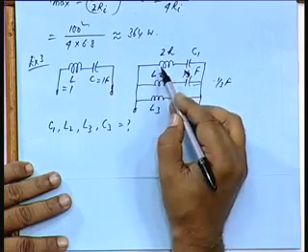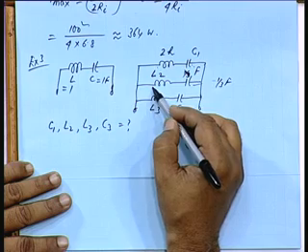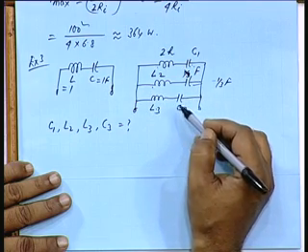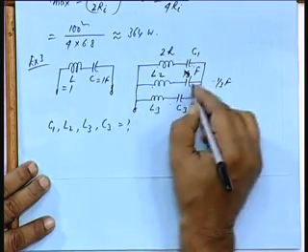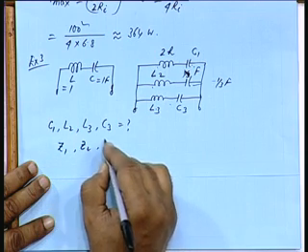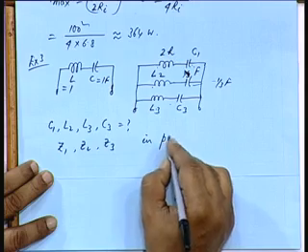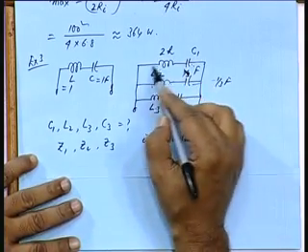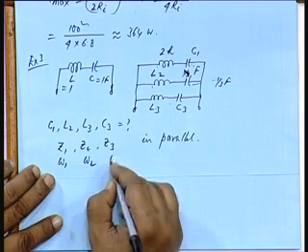Let us see, in general there is a resonance frequency for this impedance, there is a resonance frequency for this, there is a resonance frequency for this. All right. Since all of them, say I can call them Z1, Z2 and Z3. So, Z1, Z2 and Z3, they are in parallel. At resonance corresponding to this, the resonance frequencies are say omega 1, omega 2 and omega 3.